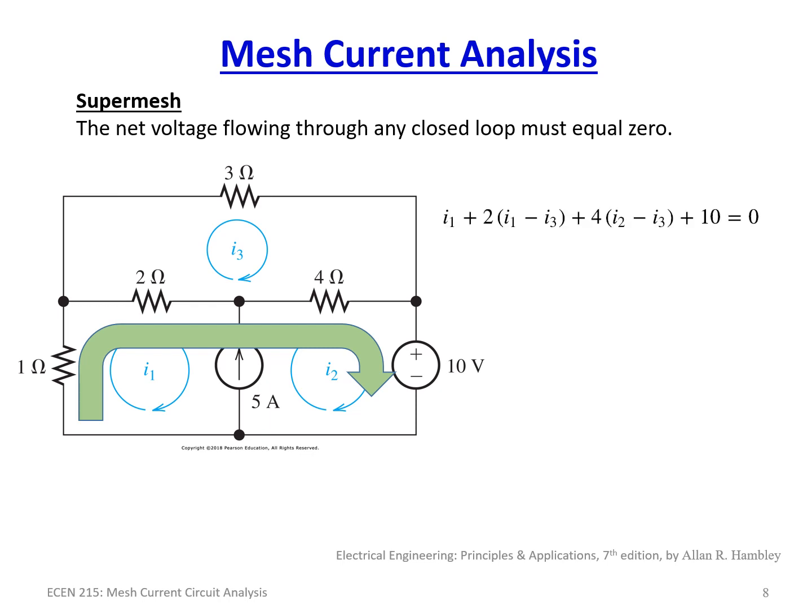Well, we have 1 ohm times I1, so this voltage drop here, we're going to start here, so we have that drop, that's this piece. And then we have 2 ohms times I1 minus I3. Now, you've got to make sure that you take I3 into account, because I3 is running through the 2 ohm resistor this way, whereas I1 is running through it like this. So the net current through the 2 ohm resistor is this times the 2 ohms.